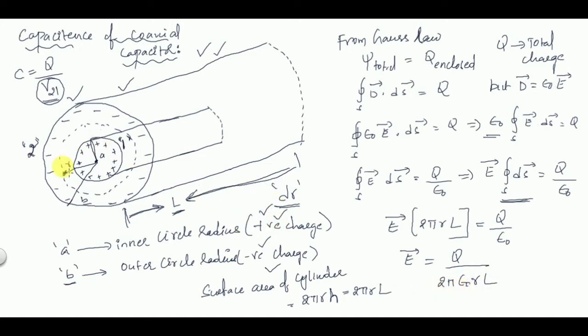Okay, so that total change in electric field intensity is around the radius, so we are taking it as a_r cap. Since here we have taken r, we are taking it as a_r cap. If you consider rho, you can take it as a_rho cap. So the change is with respect to the radius of the cylinder. We have taken r, so I have taken a_r cap. So this is the electric field intensity of the coaxial capacitor.